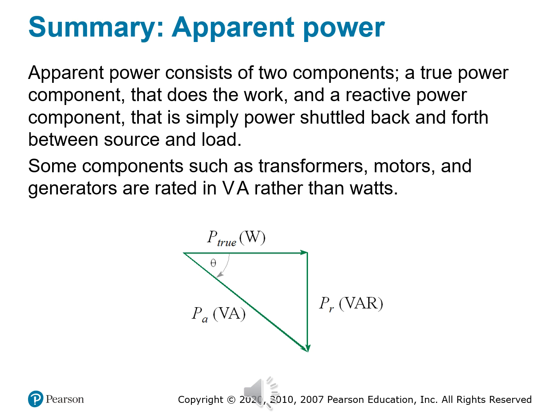If you go to your parts cabinet and pull out any of those transformers, I promise you, they have that label on there. But the bottom line is apparent power, P sub A, in volt amps, is going to equal the total energy flow capacity. True power is in watts, and that's the actual energy that's consumed. And then the reactive power, to repeat one more time, is in VARs. That's the energy that's cycling back and forth.